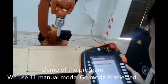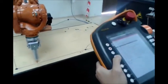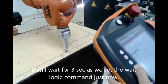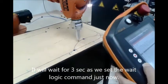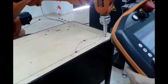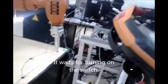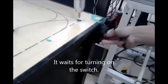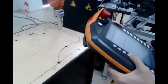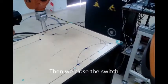Okay, you can see this is a point-to-point motion to the first point, and then linear motion to the second point. Here we will wait for 3 seconds because we already added the wait logic function. After 3 seconds it will move again in circular motion, and over here we already set the wait for logic function, so we need to open the switch here so it will continue to move. Okay, then remember to switch off the switch here. Circular motion, straight line, circular motion.